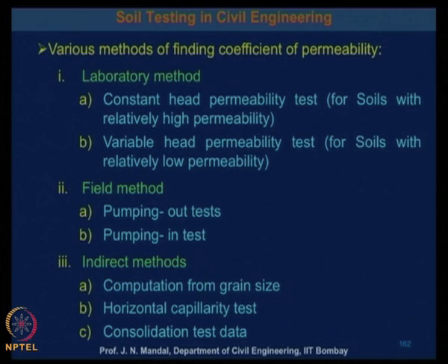There are laboratory methods: the constant head permeability test, particularly for soil with relatively high permeability, and the variable head permeability test for soil with relatively low permeability.